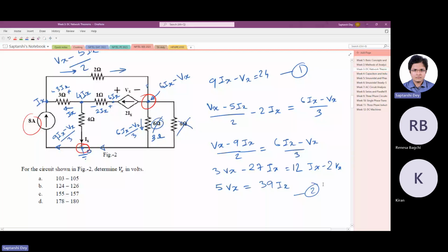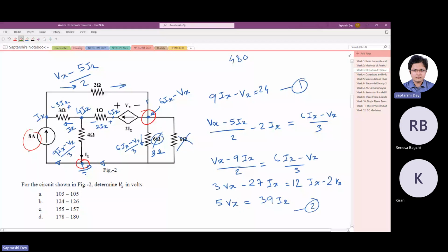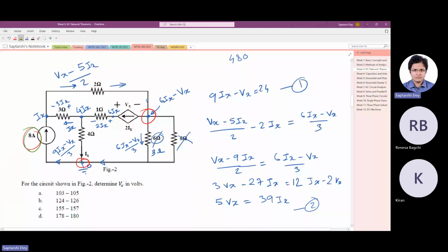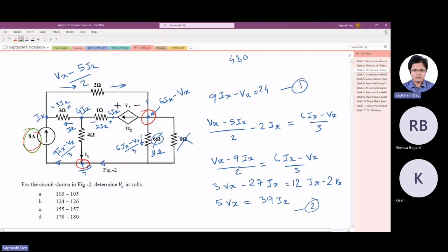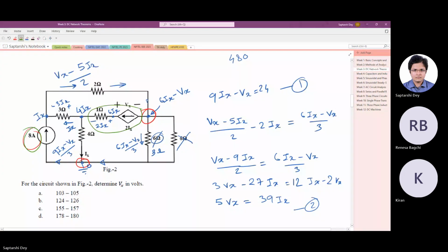Maybe. Thing is, there are two problems here. One problem is this current source. We do not know the voltage across it. Second thing is, in this branch, there are two series elements. Had this been one element, we could have assumed some current and written the node voltage. That too we do not have. So this is more difficult. At the end, you have to solve the circuit in the way it is easiest. It's not about applying node analysis or something.